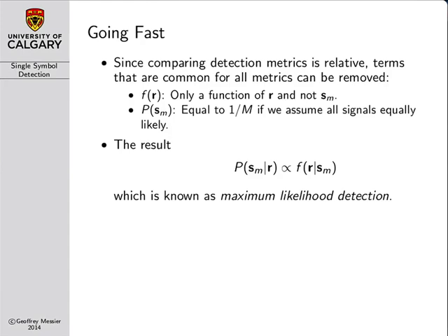And remember that if you're feeding bits through your communication system that fast, that means that your detector has to be making 100 billion decisions per second, which is a real challenge, particularly when you look at the clock rates of modern processors. And so it's incumbent on us as designers to make our detectors as simple as possible. So much of what we're going to be doing in this module will be attempting to simplify our detection rules so they are as computationally efficient as possible.